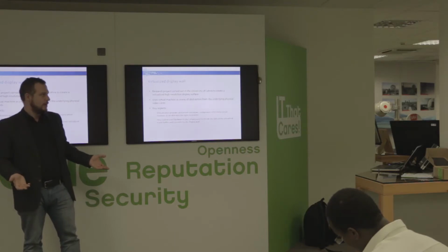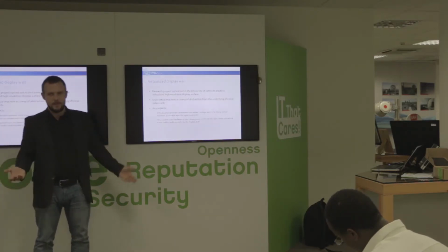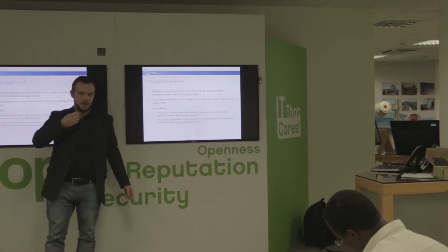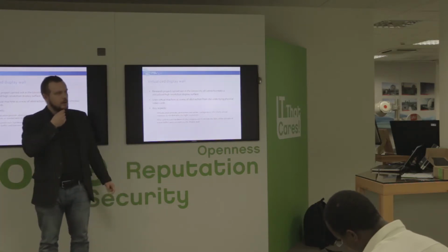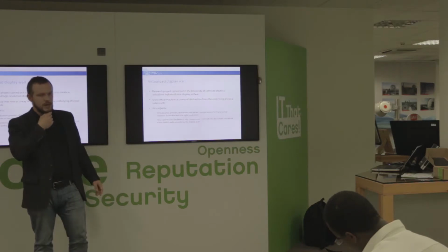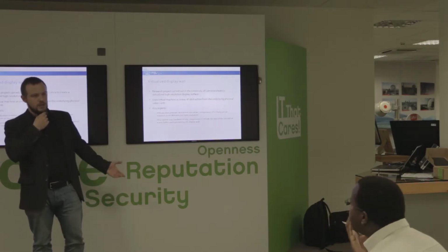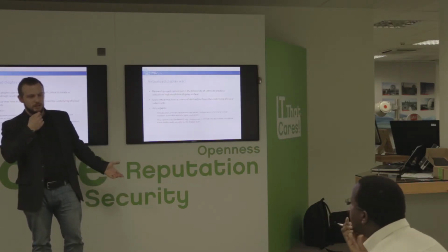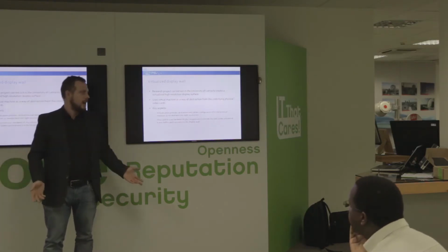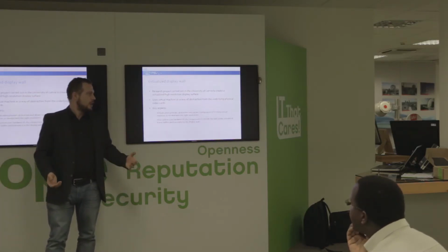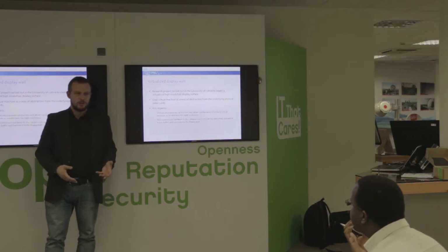Why did we choose Raspberry Pi? Honestly, we could have taken any embedded system which allows the needed codec, but Raspberry Pi was at that point one of the cheapest and one of the easiest to begin development with. They had a really open API, and they supported the OpenMAX standard, which was really easy to use to write the software for the coding.